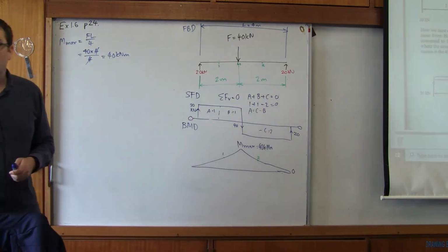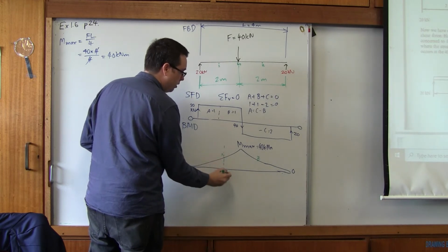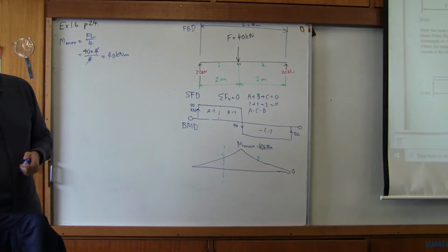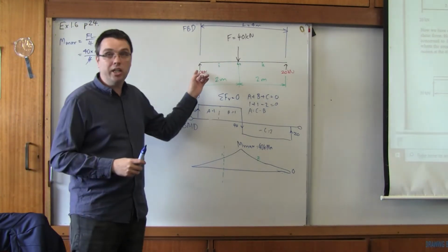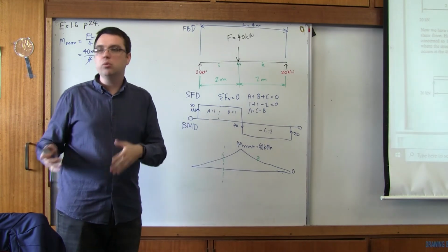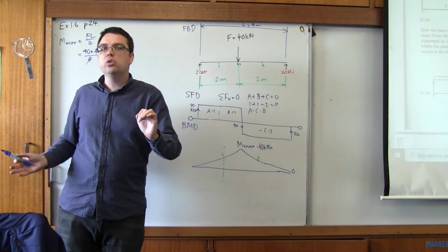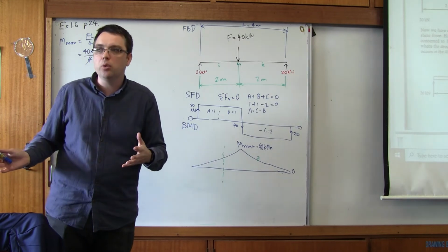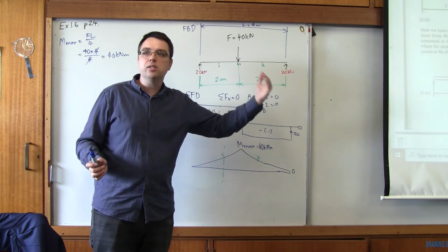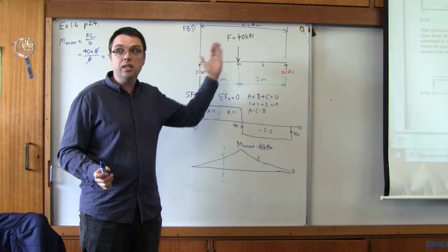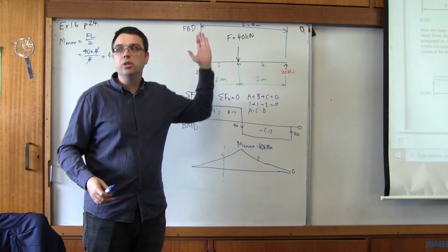What we're going to say is, the force on the left-hand side, we're going to start with 1. The sum of the moments are equal at every single location. We've proven that. We've talked about it with reactions. The reason why we like to take reactions from the edges is because we have two unknowns, and we can choose any location. We just choose one of the unknowns to eliminate an unknown. But at every single location on this beam, we can take the sum of the moments and have it equal 0. What that means is the moments on the left-hand side have to add up with the right-hand side to 0. So if this is minus 10, that side will have to be plus 10. If this side is minus a trillion, this side will have to be plus a trillion.